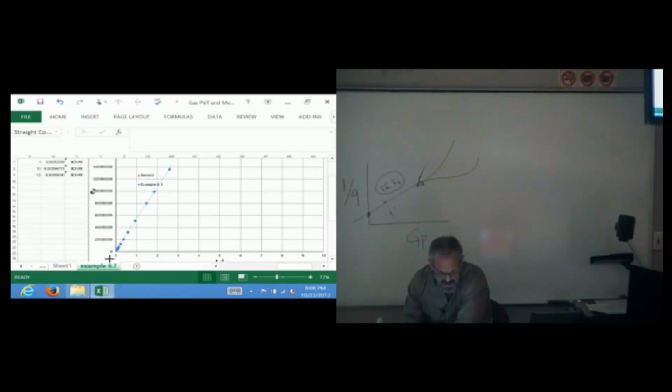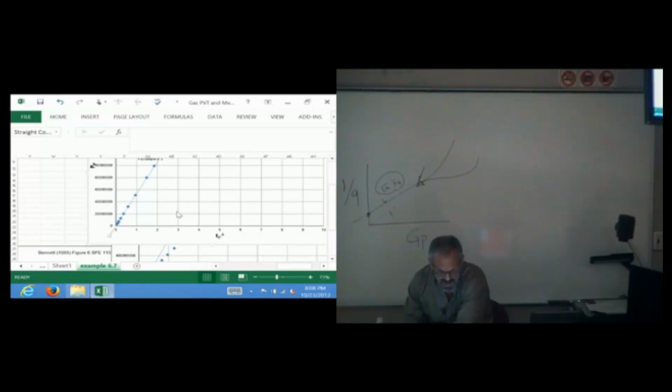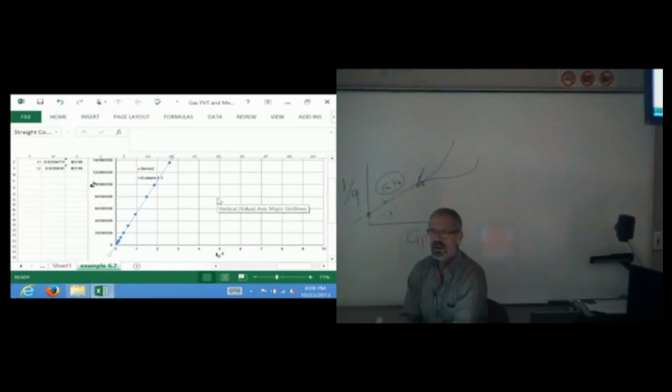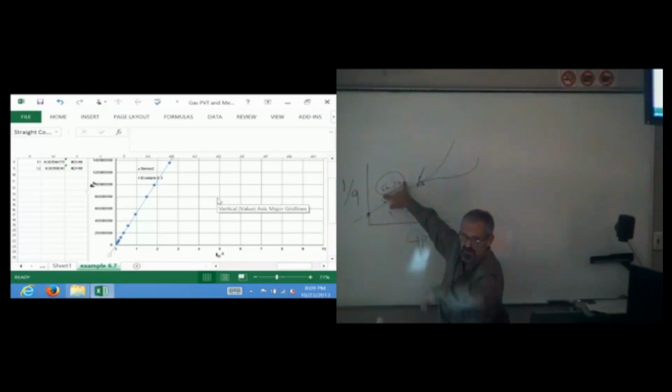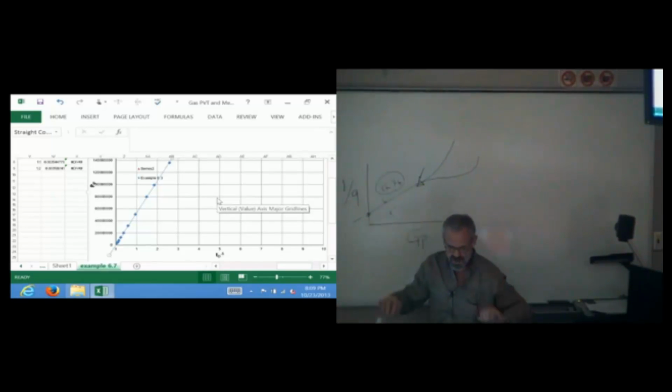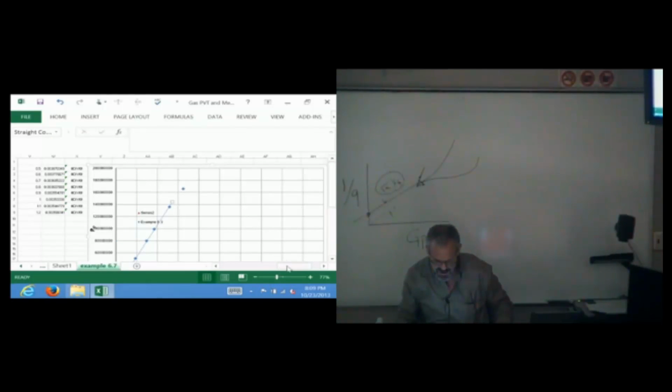And it's got to be a straight line. I got half slope. Remember, I've got half slope on my log-log plot and my log-log derivative, and I've done a type curve match, and my type curve match tells me that I should have linear flow. I got 3 reasons to believe, besides the fact that all of the data go through a straight line, that this is the slope that I'm going to use to calculate my fracture half-length. I'm actually going to calculate this coupled parameter, the square root of kxf, but I already got perm. I divide that by the square root of perm, and I'll have my fracture half-length. Okay, I got the equation. I am ready to go.